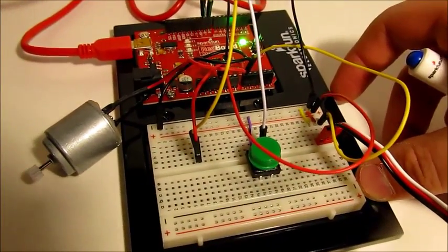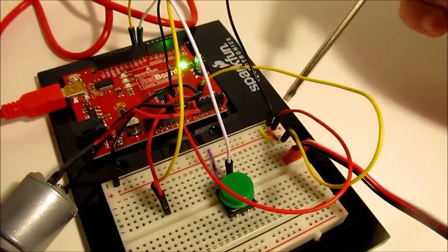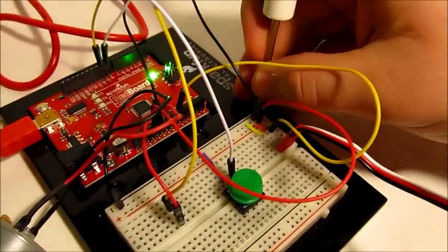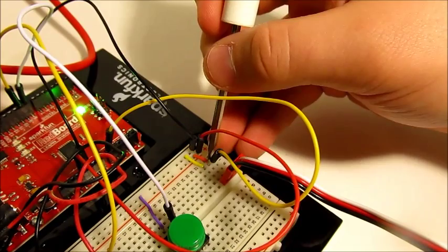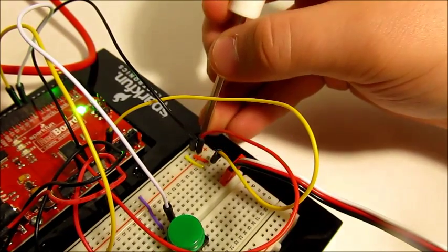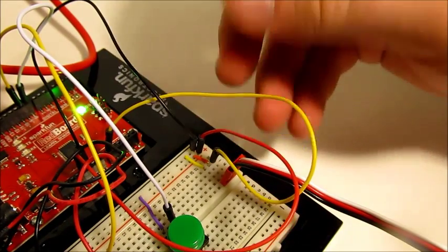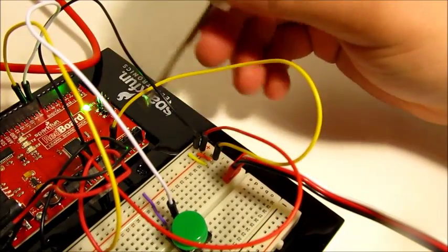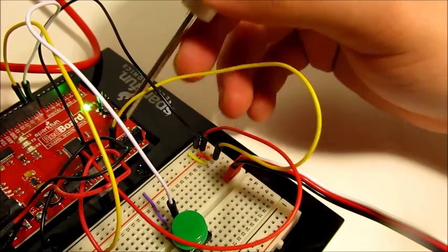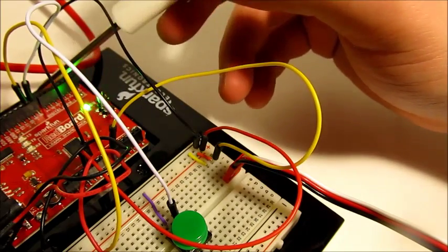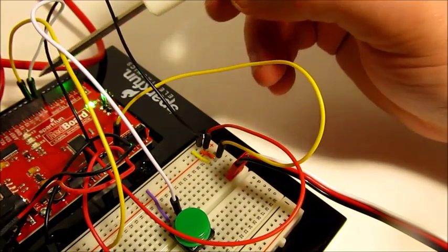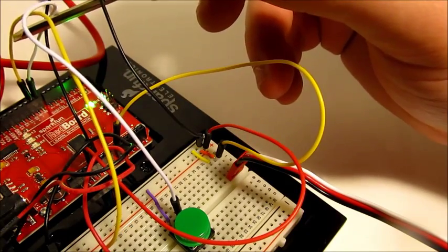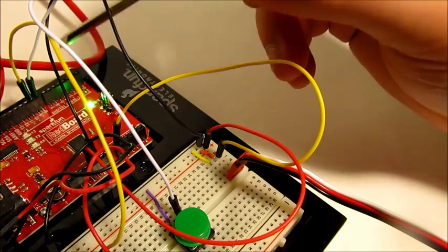The wiring setup for this is the same as the past two objectives initially, using the potentiometer, with power and ground to the potentiometer from the bus, and the signal wire going to analog pin 0. This is then used in the code as an analog value, and read to be a number between 0 and 1023 based on the input voltage.